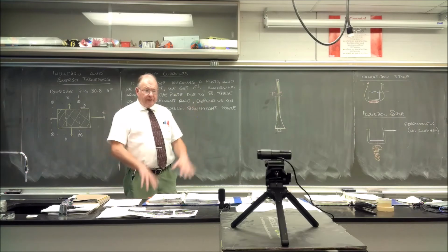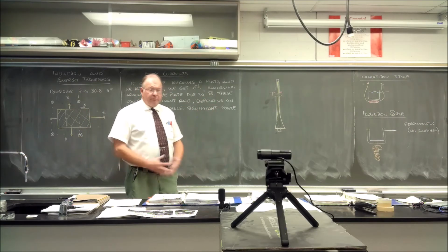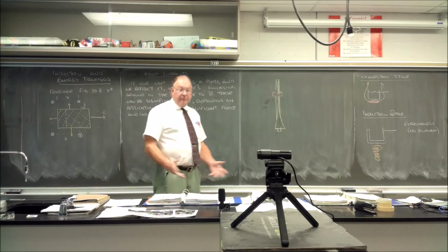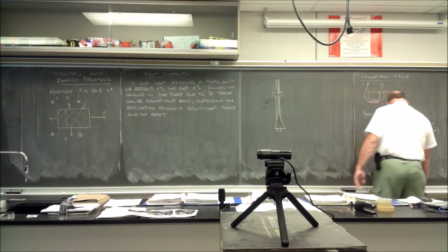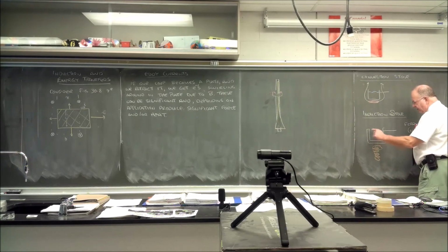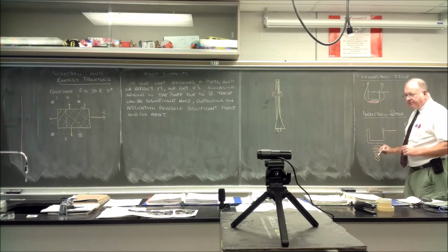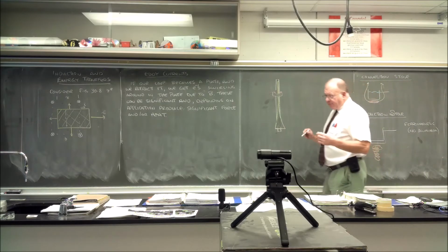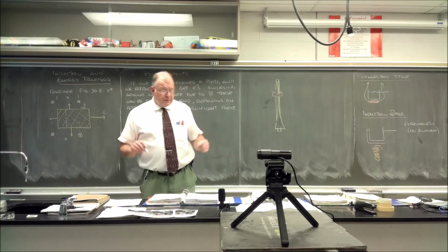The magnetic field will be constantly pulsing and changing direction, maybe just through the standard alternating current from the house or something like that. Cycle, cycle, cycle. Now what this is going to do is produce eddy currents in the steel part of the pot. The porcelain is irrelevant. The steel part of the pot will get hot, the whole thing, not just the bottom. It might be the bottom gets a little hotter because it's closer, but the sides will heat too.